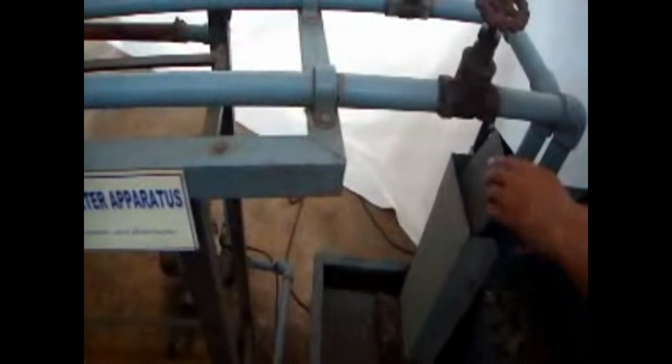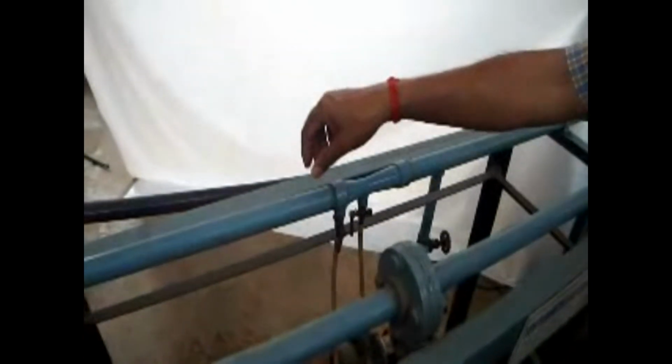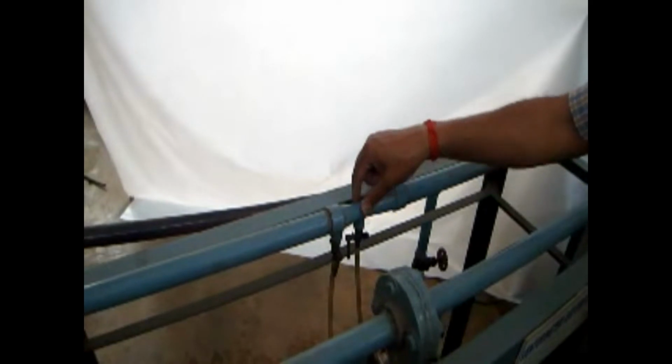So it's the supply of water through Venturi, and flow is here. It is discharged. When we are measuring, we will shift this to here, otherwise we can bypass it. And let us see, because the flow has stabilized now, full flow condition of this pipe. Let us measure what is the head difference between the supply side and the Venturi throat.